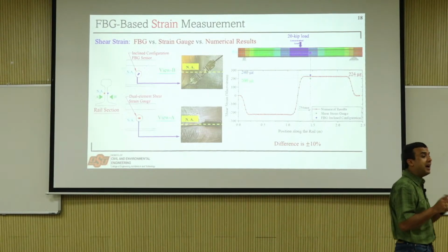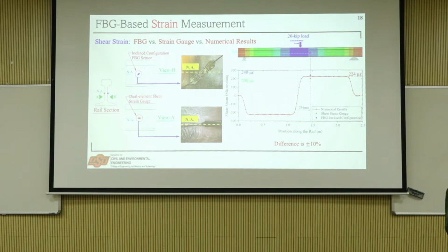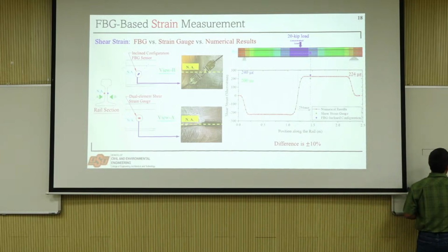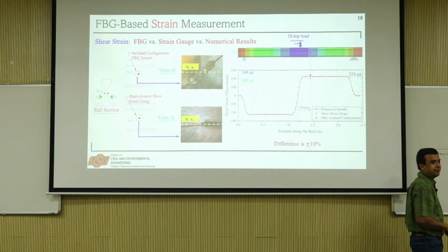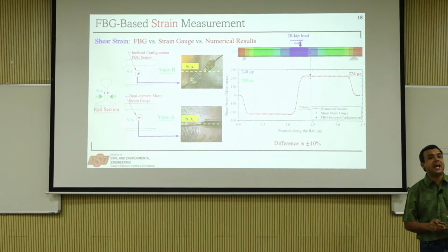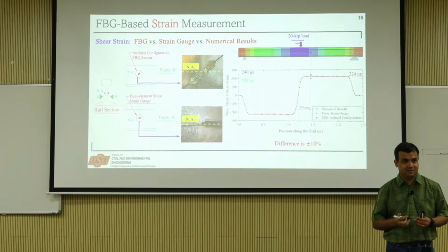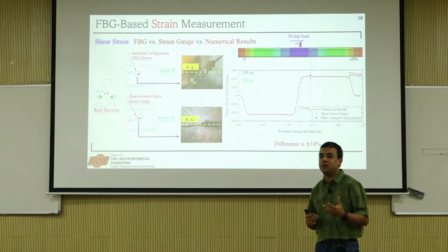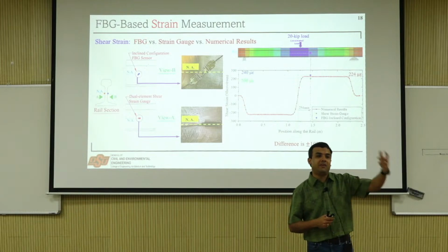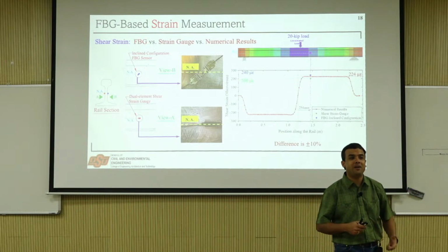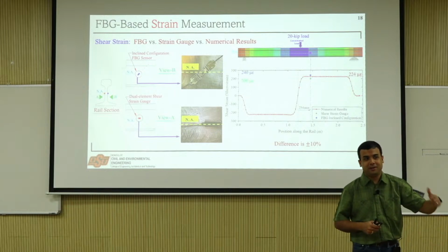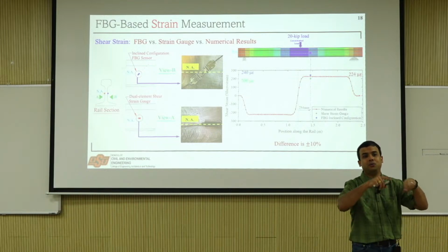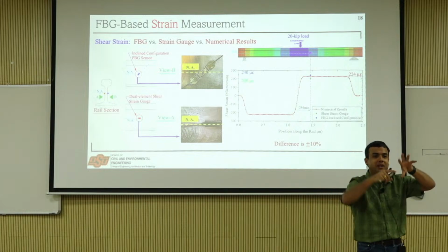And the advantage of fiber optics, folks, what you'll see is that we are now installing it in the axial direction. We are measuring axial strains, and then using classical beam theory to go into curvature, bending moment, shear force, and the fourth order equation where you get deflection.